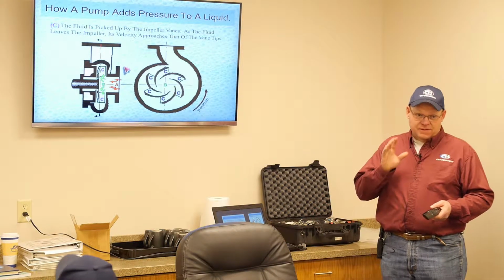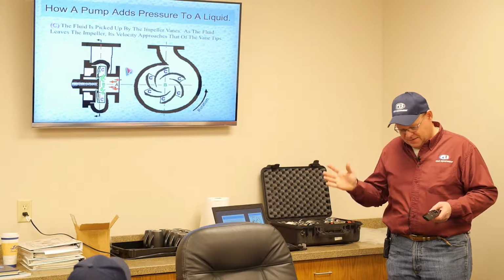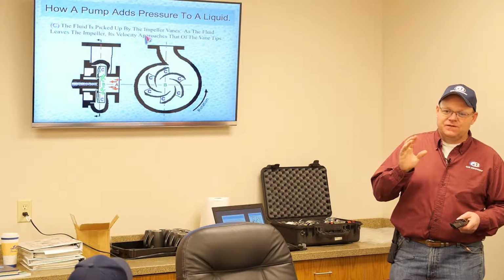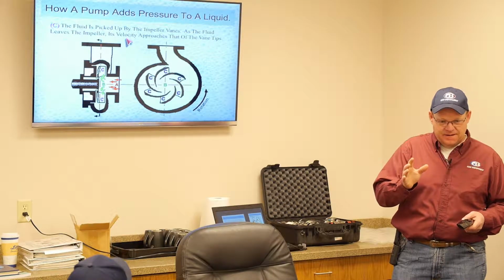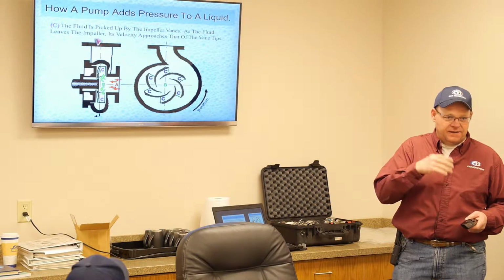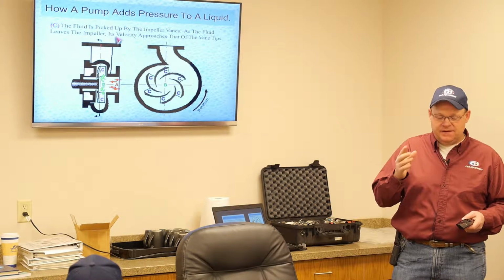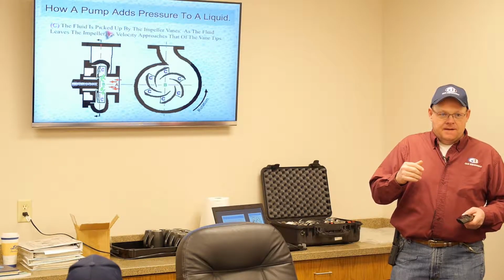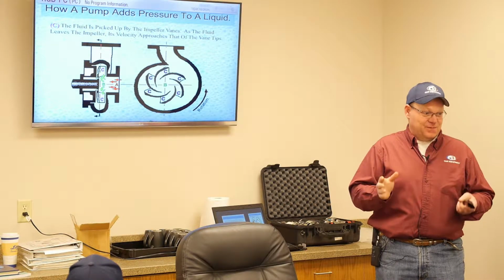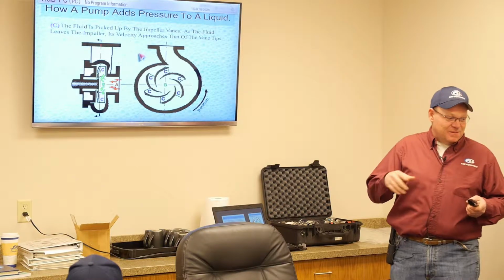So while we're on that topic, just as a little whimsical quiz here, what is the best way to check, what do you do first when you're installing a new pump to verify rotation on an electric motor? Everybody deals in 60 hertz here. To check rotation, the first thing we're going to do is make sure it's not coupled together, right? Check rotation on the motor.